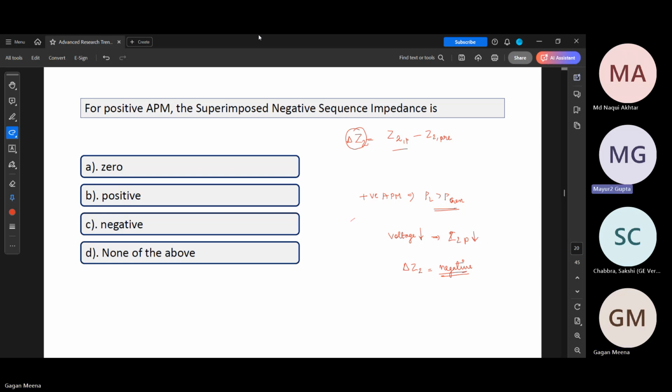Again, I'll try to explain in a different way. Since you talked about microgrid, reactive power is a local phenomenon. So you can have a local remedy for it. A capacitor bank or an inductor would be a local remedy, or a STATCOM is a local remedy for it, to maintain it accordingly. So even in a microgrid, this is applicable. Yeah, that is true. We can use a capacitor bank even in a distribution system. We use capacitor banks to boost voltages.